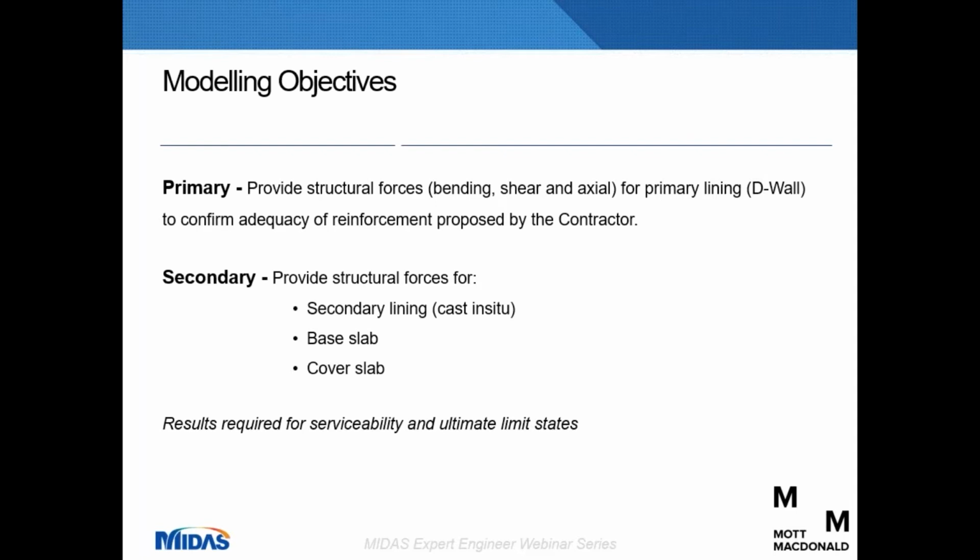So part of our role in the project was to provide independent checking of the contractor's wall design of the shaft. So we needed to create a numerical model to determine the design forces in the primary lining, which was, as I mentioned, a 1 meter thick diaphragm wall.